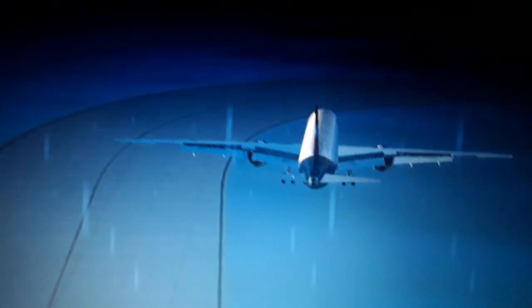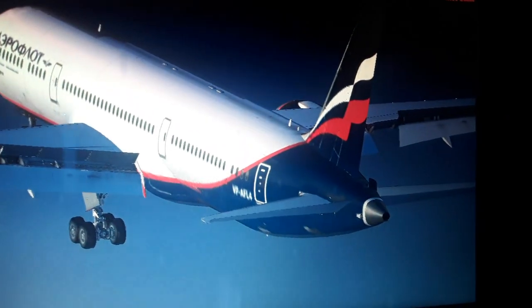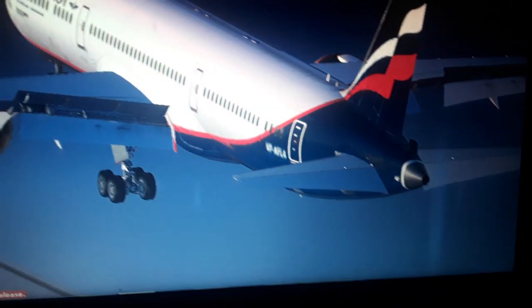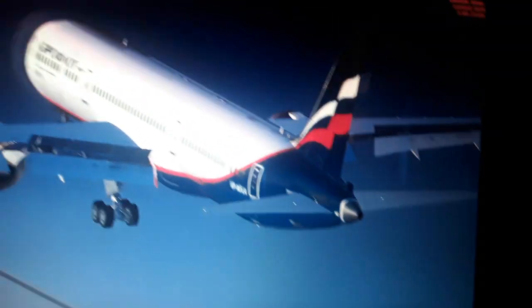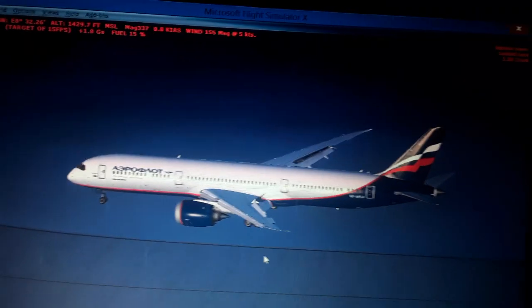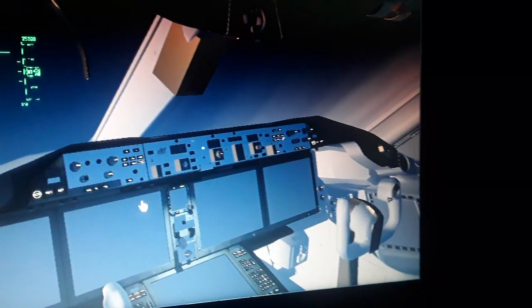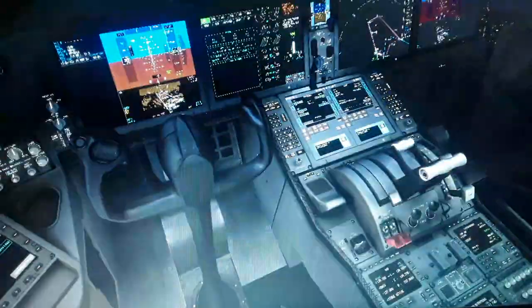So this is the horizontal tail here. You trim up and trim down in flight for pitch up and pitch down. The aircraft, you trim the whole surface up and down. It balances through the center of gravity and the forward wings, the mean aerodynamic chord position. So we have the flight controls also. We can see a couple more things.